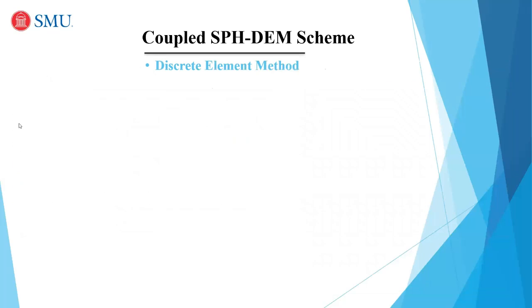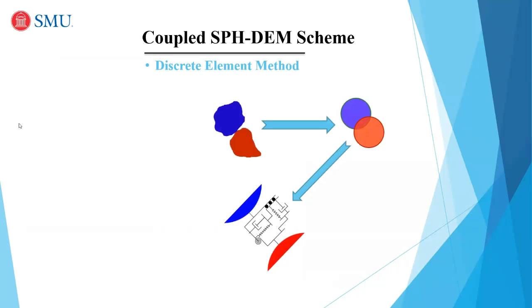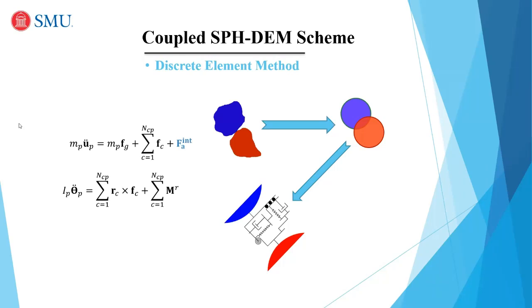I don't want to go through many equations, but quickly, this discrete element technique is really very simple in concept. We simplify the grains, even though you can actually have them as irregular shape nowadays. But in this particular study, we simplify them to just spherical particles. And at the contact, the whole modeling thing is at the contact, there are springs and dashpots to model the force displacement law. Once we have a definition of these contact stiffness and dashpot properties, we can get forces at the contact. So each grain will be acted upon by so many forces, and then we solve Newton's second law of motion to get new particle position and rotation.